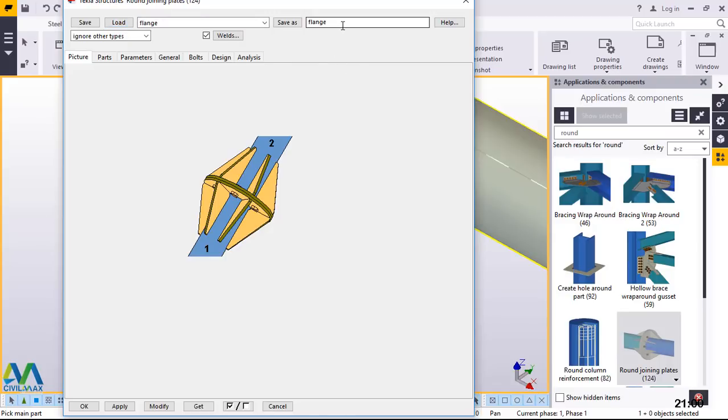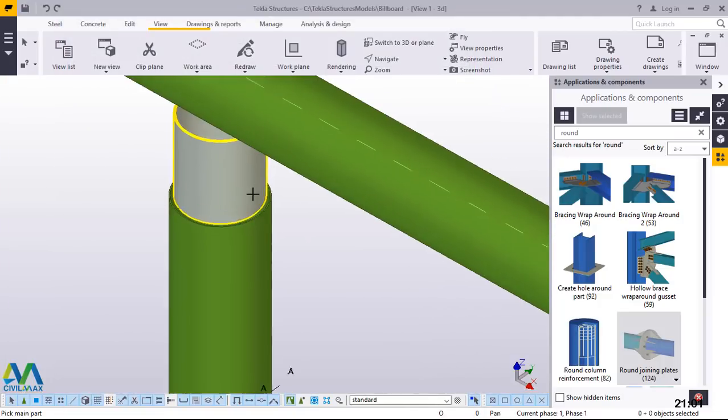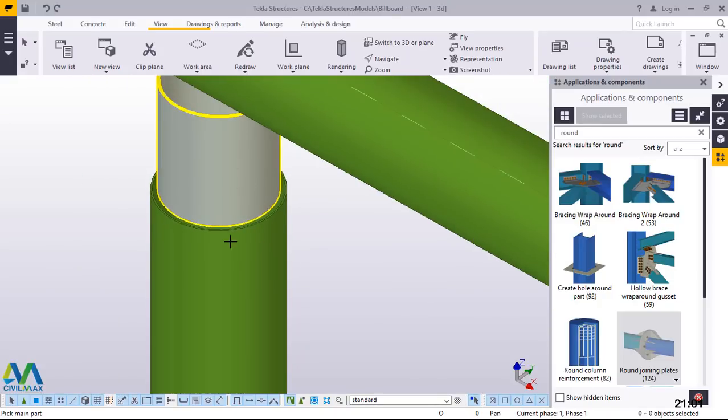Remember, you can do a similar thing by the moment you've done a connection. Please just save it, because if that particular connection you use it frequently, you can save it, give it a name and save it, and you will apply it in whichever connection that will be right for it. Now I'll go ahead and click load here. I'll click modify. I'll come to apply and give it an acceptance by clicking an OK button. Now I want to connect these two members. I'll pick on this and pick on this and give it time to load.